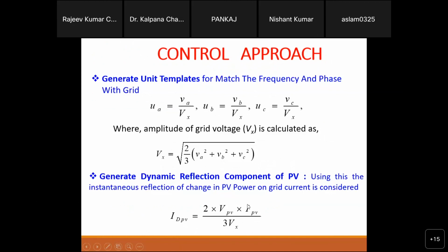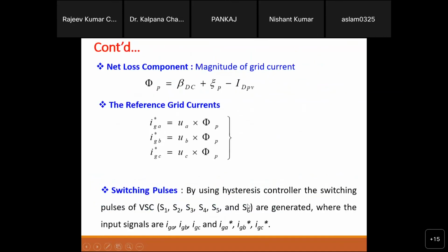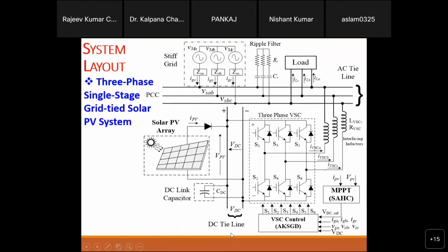This is the PV power. Because the amount of power you are going to feed is going to decrease, right? Simple. So at that time the power becomes the PV power minus all those DC loads. Sometimes you will see someone attach a battery bank here also, with DC-DC bidirectional converters, or EV charging. So you just change that one term, and then it will look like that.